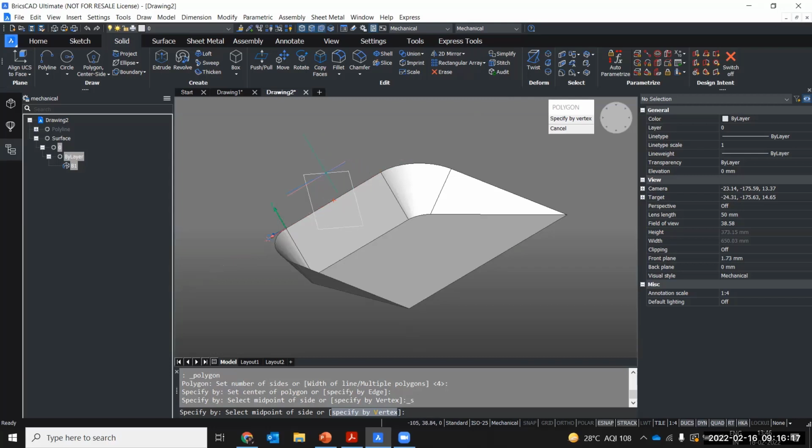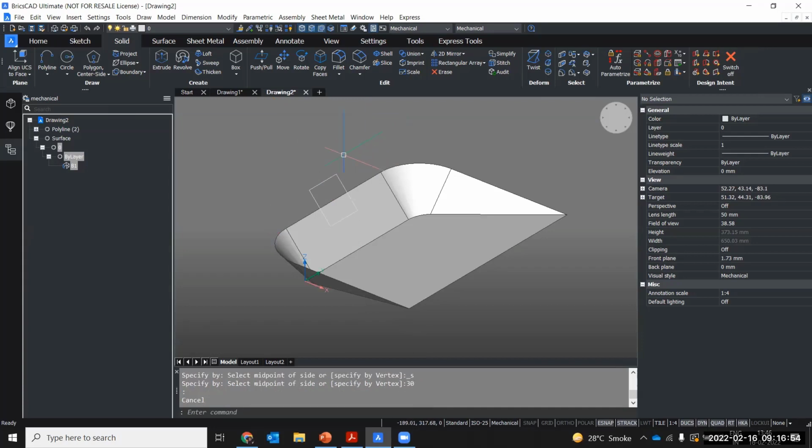Okay, so you can enter the width. The thing that is happening over here is my rectangle is rotating around across the axis. So I'll just press shift again to lock the rectangle at one particular axis. And now if you see, I move my cursor, you will not be able to rotate your rectangle. If I press shift again, now it will be free. If I press shift again, now it will be locked. So now it's locked to that particular axis. So the dimension that I would be entering over here is 30. Hit enter, and you have the rectangular profile.